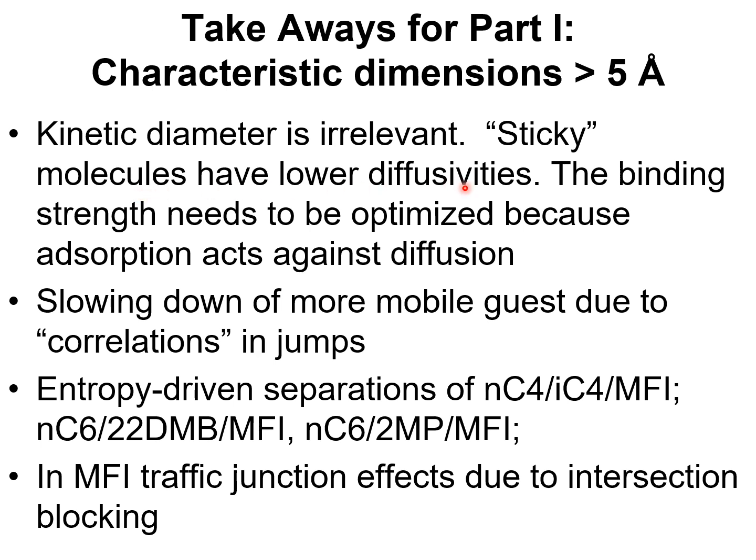Another point that was emphasized is that pencil-like molecules such as carbon dioxide and nitrogen jump lengthwise across the channels, and it is pointless to talk in concepts of the kinetic diameter. Moving on to the second class of materials, in which we have window or channel dimensions larger than about 5 angstrom. Here again, we have emphasized that the concept of the kinetic diameter to correlate component permeances is irrelevant or not applicable, because